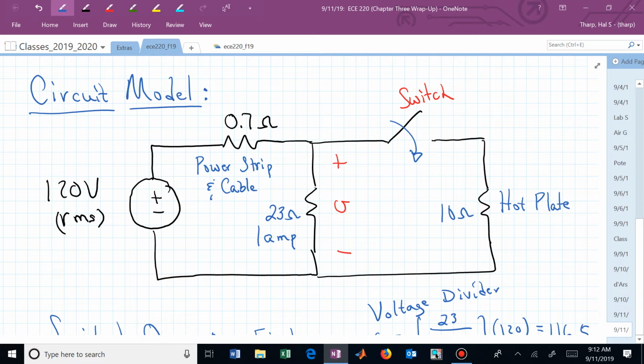So now we have really the lamp and the hot plate in parallel, and we can combine those resistances as resistors in parallel, and then we have an R2 new, or an R2 hat. We've been sending these R2s to a party when we have them in parallel. We now have an R2 equivalent, but now we can use the voltage divider again with a modified R2.